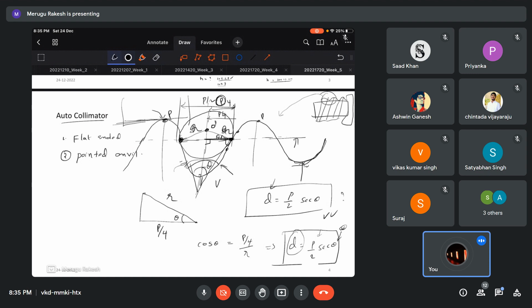Yeah, for internal measurements, there is a process. Suppose I have an internal feature, I just pour some wax inside, fill the cavity completely, then unscrew the wax and measure. It is like measuring the outer screw only. So that is the process we use. There are no special instruments for that. We just put some wax, solidify it, take it out and measure. So these are the main concepts involved.